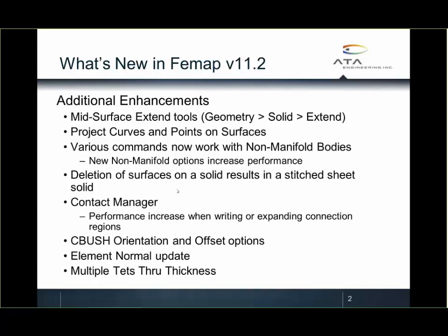You can also project curves and points on surfaces from within the meshing toolbox. So if you already have a mesh on your mid-surfaces, you can project those curves and points, and it'll automatically update the mesh to match your changes. They've also changed a few commands to work with non-manifold bodies. That's very convenient. You can now delete surfaces of a solid, and it will allow you to do that.